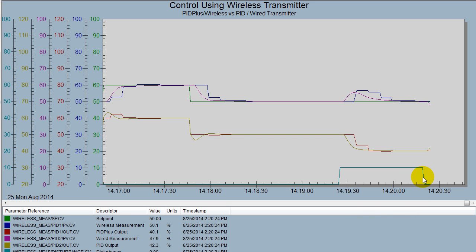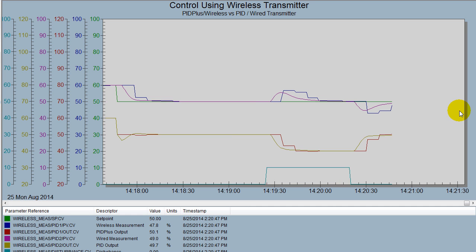When we do that, we notice that again we see the change in the process parameter due to the disturbance, and then the control is responsible for correcting for that. We notice again that there is some delay in the wireless control responding, just due to the fact that the communication is only every 8 seconds normally for the wireless communication.